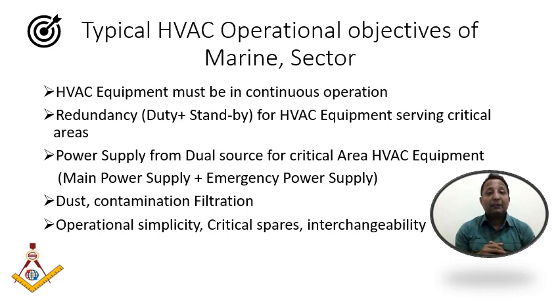Then interchangeability: try to select the AHU model, AHU motor model, fan model or ventilation fan model as similar and close to each other as possible, because when a failure happens to one, the spare part is common. So you don't have to buy a different capacity motor, because if one spare is there, you can easily interchange it. So try to standardize the requirement as soon as possible by being flexible in the design. This is the purpose of talking about interchangeability. Now let's move on to the next slide.